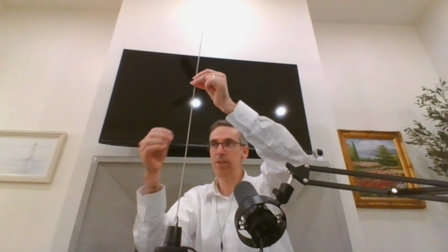So if you don't really care which direction you're sending or receiving the signal, you want to use something basic like this. If you want to aim it, there's a Yagi antenna, which is like a series of these getting smaller and smaller, and it basically aims the wave in one direction, and you point it. There's a horizontally polarized wave, and there's a vertically polarized wave. So if it's vertical, it's going out this direction. If it's horizontal, it's going out that direction across the horizon. So it depends on which way it's polarized and aimed.